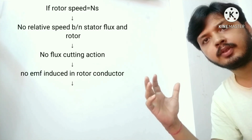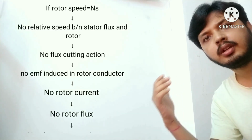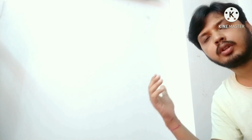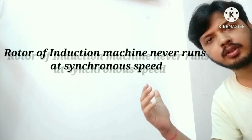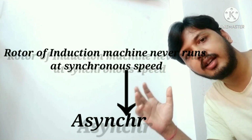Thus, EMF is not induced in the conductor, and zero current is developed in it. Without current, torque is not produced. Because of the above-mentioned reason, the rotor never rotates at synchronous speed. The speed of the rotor is always less than the speed of the rotating magnetic field. That is why induction motor is called asynchronous.